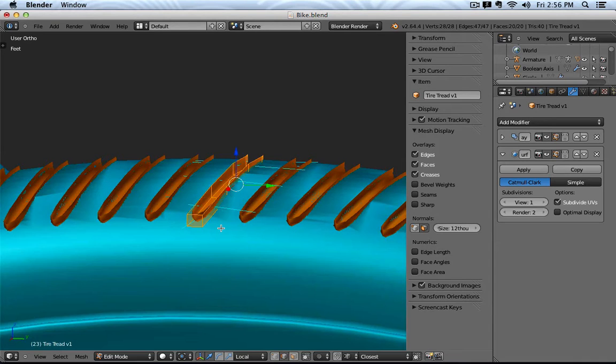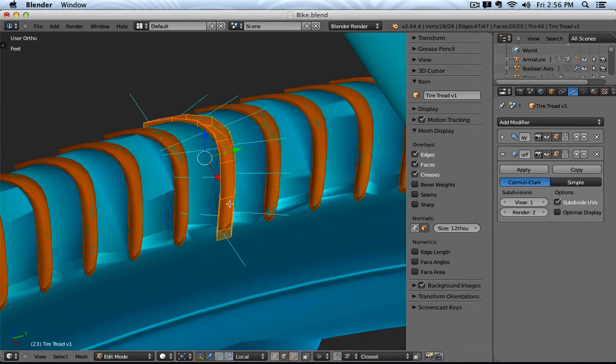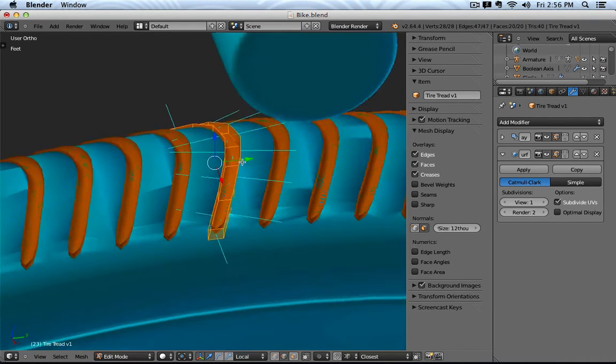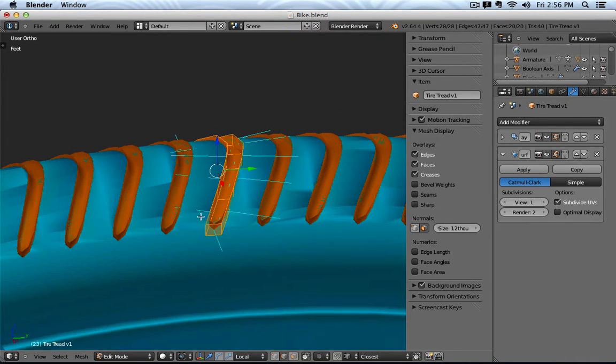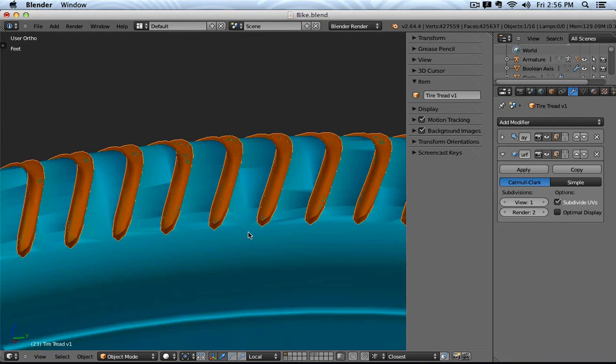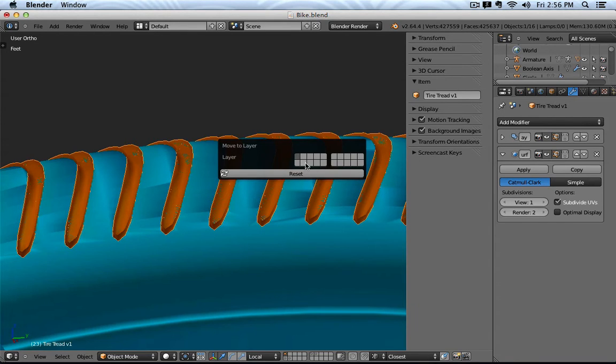That is, for example, similar to Alias when you click a surface and you say keep or remove. And here we can't click a specific surface to say keep or remove. We simply, by the orientation of the surface, if it's facing inside or outside, can say what part should be cut out and what should remain. Now this orange surface, maybe I'm putting onto this layer because I don't want to see it.